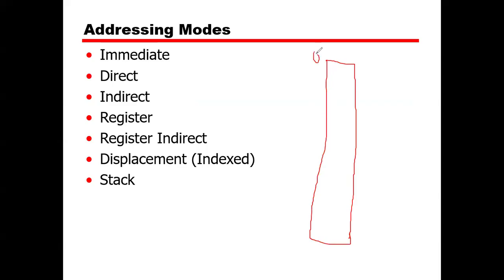From 0 to 16 gigabyte minus 1 to 16 giga. Why don't we say 16 gigabyte, guys? Because we don't know how many bytes there are in the same address. So if the chip is a 16-bit chip, then this is 16 giga 2-byte addresses. So we say 16 giga addresses, like in von Neumann. We said 1000 addresses, and each address has 40 bits. So we say 16 giga. If we say 16 gigabyte, assuming that it is byte addressable, then it is 16 gigabyte. Yes, it means the same thing.